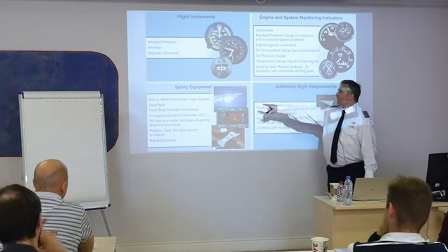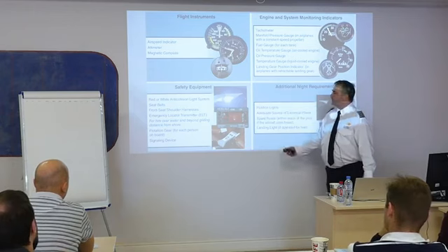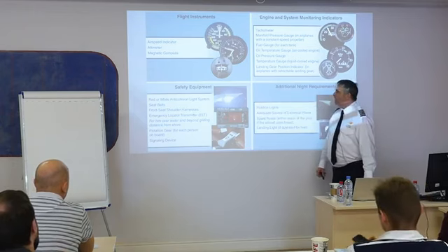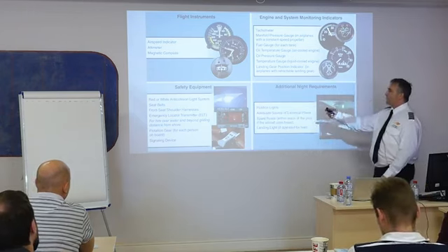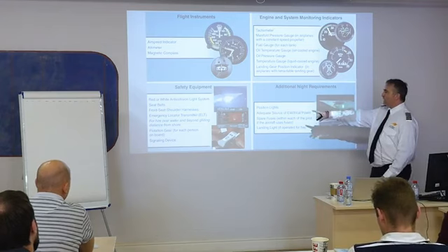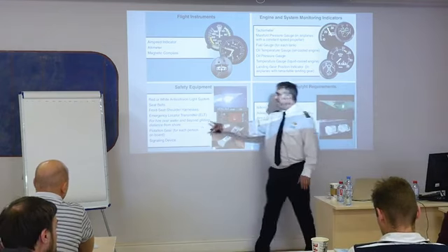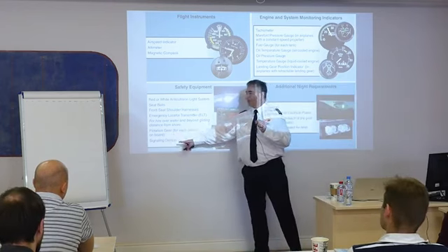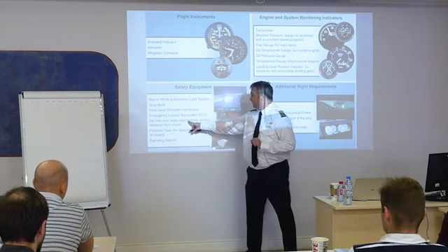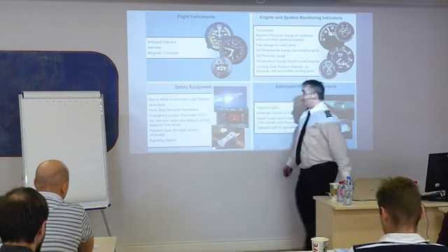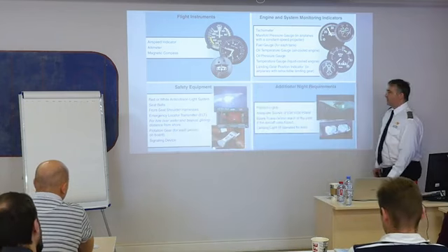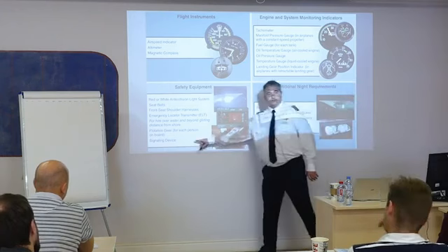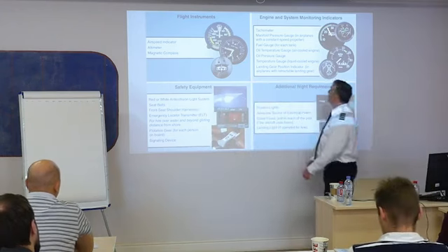Safety equipment. You need a red or white anti-collision light. Seat belts. Front seat shoulder harnesses, emergency locator transmitter. If for hire or going beyond gliding distance from shore, I need a flotation device. I had a question about flotation device, right? If for hire, over water and gliding or beyond gliding distance from shore, and a signaling device. Okay, so that's all my safety equipment.